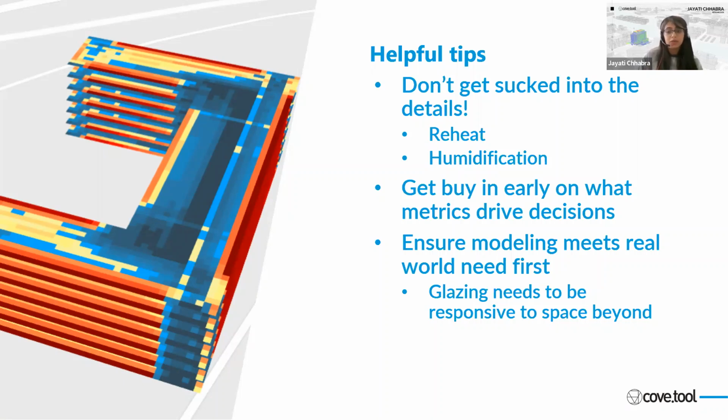And this kind of gets down to glazing. For the EUA clinic, window to wall ratio studies can be beneficial to increase daylight and be responsive to the spaces created. But I wouldn't really run it for energy, because if I do that, by that principle, no windows is the most energy efficient for a building. For the EUA medical clinic, energy was also mainly driven by lighting and equipment loads that we will see in the later slides.